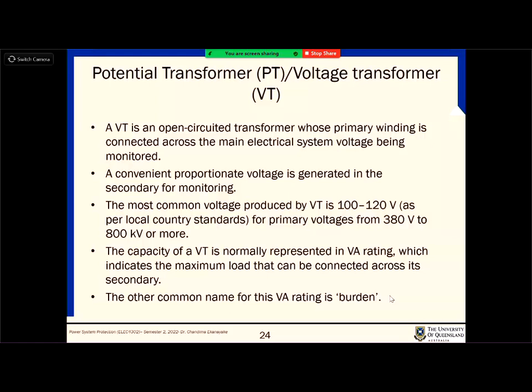Yeah, and then typically there is the accuracy of the VTs. Accuracy means how correctly you can measure the primary voltage on the secondary side, because we assume that the turns ratio gives the secondary voltage, right? Once we measure the secondary voltage, we multiply it by the turns ratio to get the primary voltage, but the real primary is different from that, right?